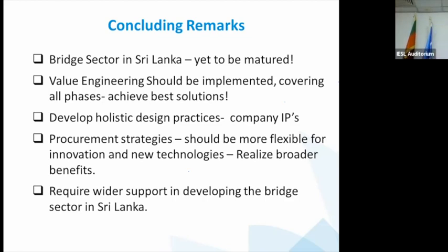The question is related to the two types of construction that I mentioned, the segmental and the full stage. When you come to segmental construction, of course, you need to ensure that enough tension force is applied so that the segments stick together. You need to apply enough such that the deflection is also controlled appropriately.